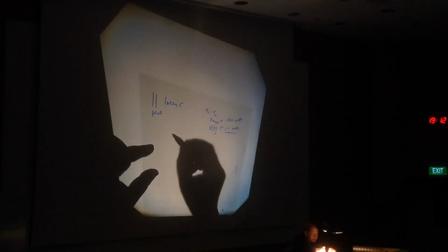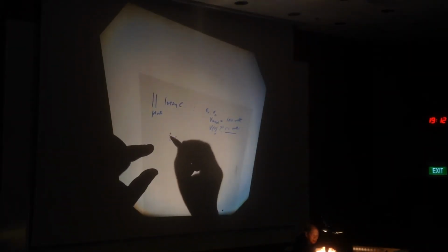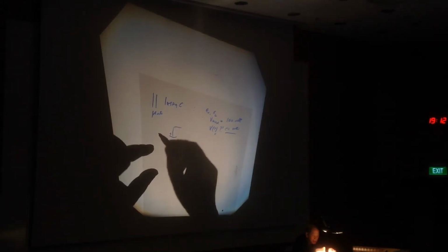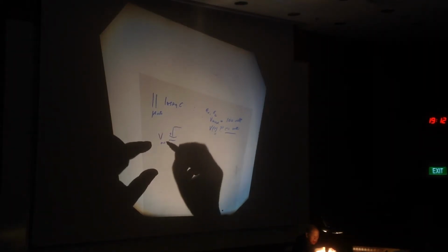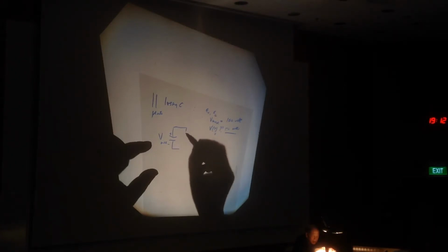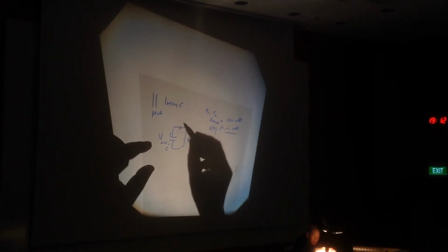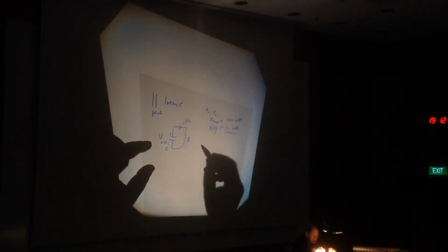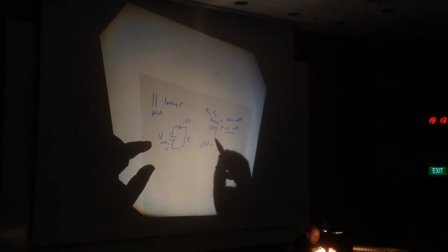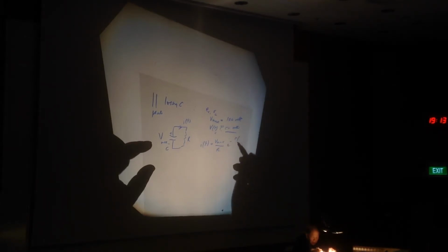The simple capacitor is charged to V max, and this is going to be discharged through some resistor. This one has got its own capacitor C and R, so this is the discharge current. I of t is simply equal to V max upon R, e to the minus t upon RC.